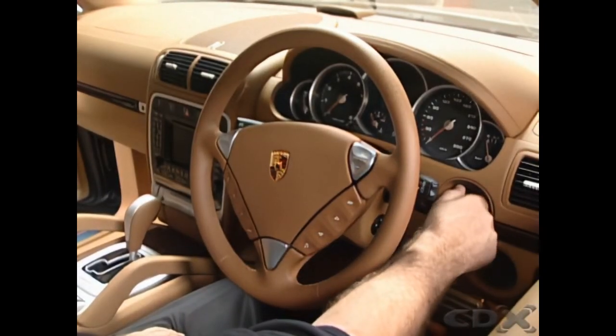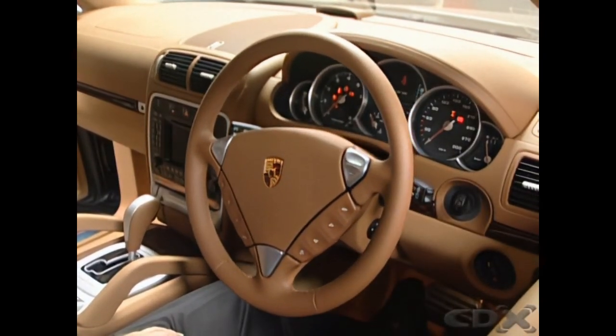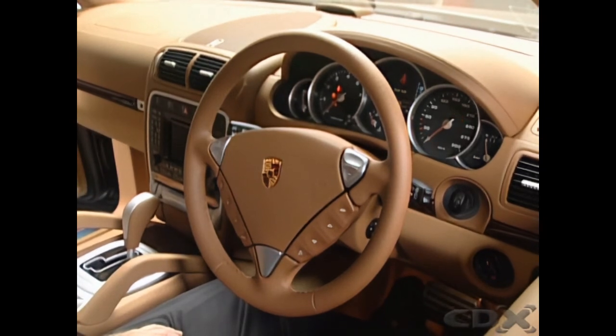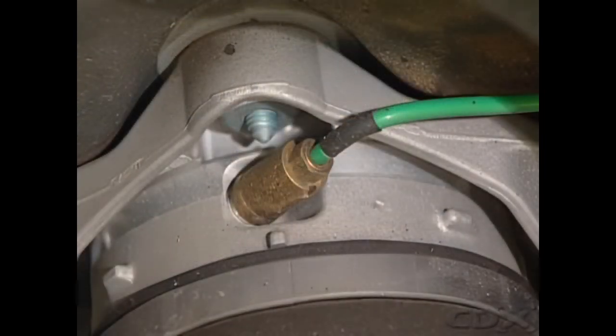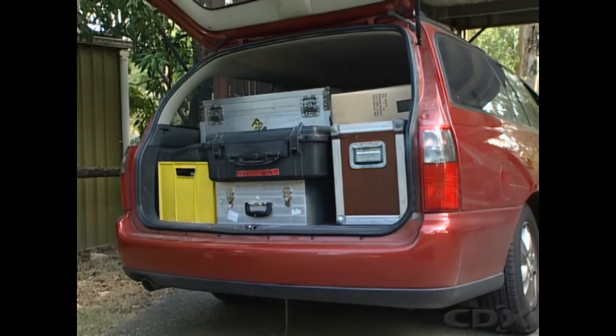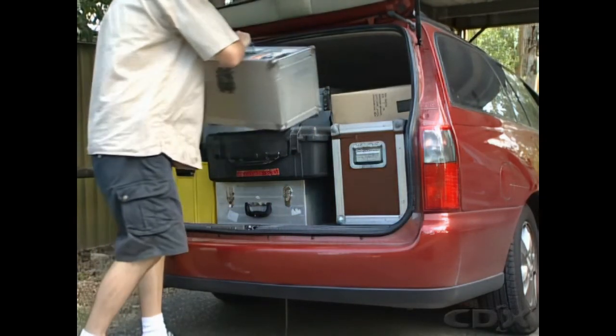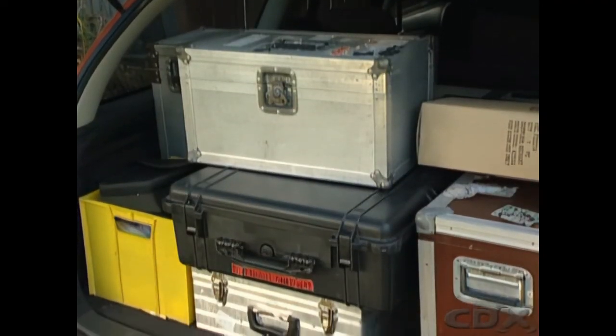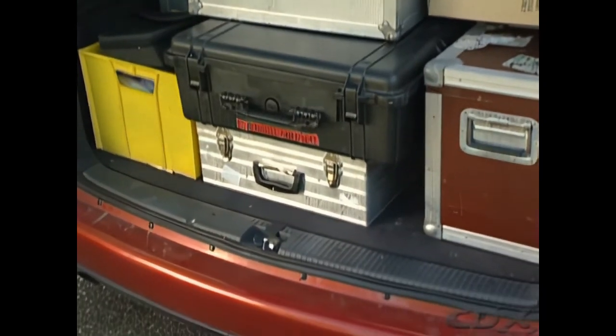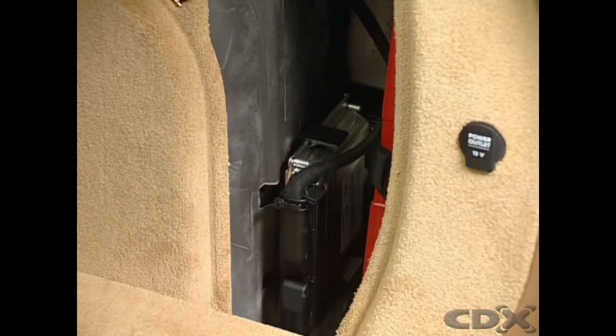When the ignition is switched on, or when the vehicle's door is opened before ignition, the control system is activated. The height sensor uses the induction principle to constantly monitor the distance between the vehicle's axle and its chassis. When the vehicle is being loaded, unloaded, or lowered due to driver command or vehicle speed, the electronic readings from the height sensor monitor the change. This is picked up by the electronic control unit and compared to the stored reference values.